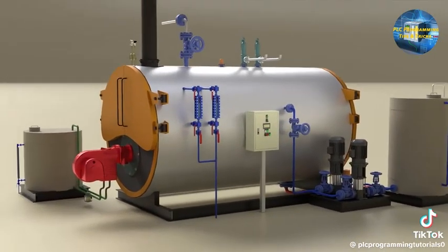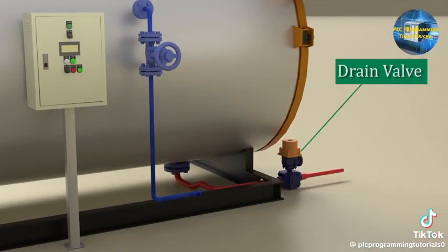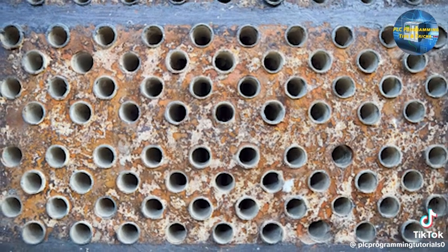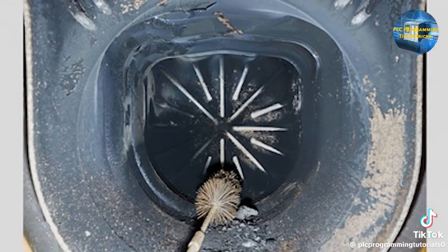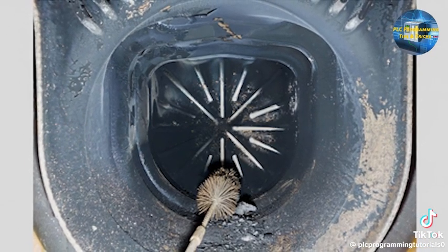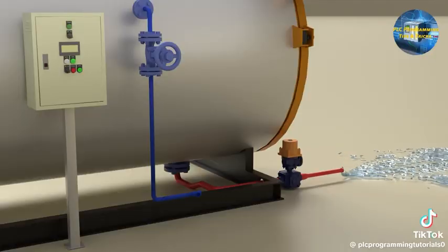Now let's see the drain valve of the boiler. As we know, in the industries the boiler runs 24 by 7, the whole week. As the water turns into steam, the minerals in it start to deposit on the inner walls and the bed of the boiler chamber, and they also turn into clinkers and stay inside the boiler. This drain valve opens maybe 4 to 5 times a day for a quick 10 to 20 seconds just to drain some water from the boiler, and this helps to improve the boiler efficiency. Draining reduces the risk of internal corrosion caused by settled debris.